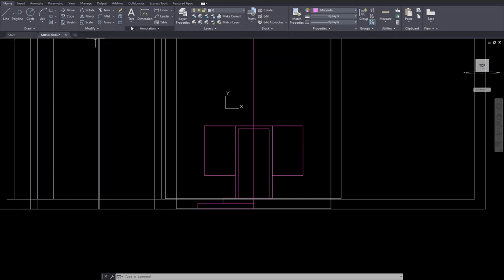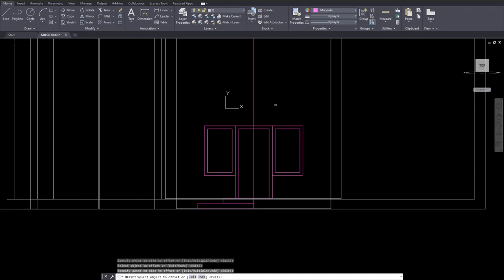Okay. So I'm going to use the offset command. And the offset command will ask me the thickness of the offset. It also remembers 0.03 from the last application. Enter key, and select the window, click inside, select the window, click inside, and now you have 0.03, okay? All right, and then you go occasionally and save your work. Good.